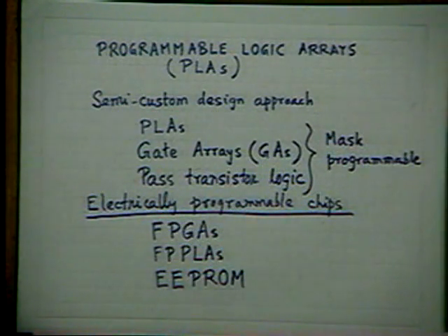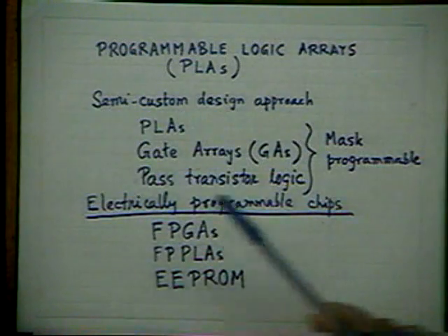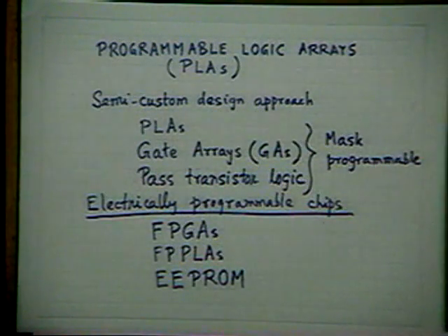We shall be discussing them in some detail afterward. We shall see that field programmable means you have PLAs prefabricated. The transistors are all there in suitable locations. The array is there. Now, instead of connecting them in the mass fabrication while manufacturing, I try to think of something which can be done in the lab.